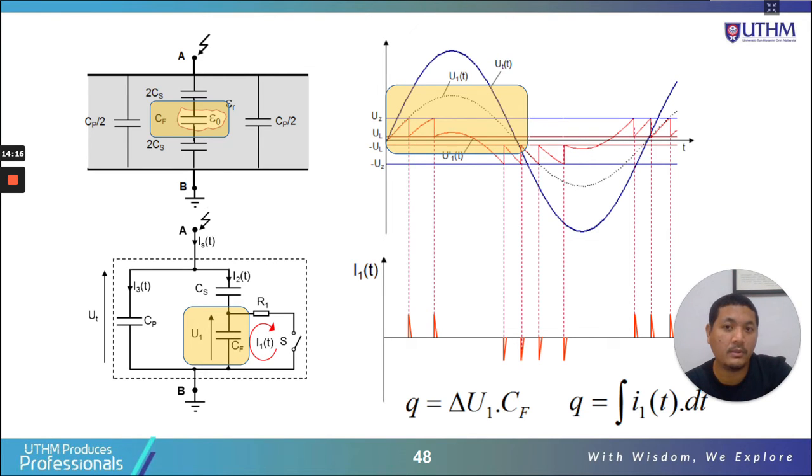When I say discharge happens, it means there is an electrical breakdown inside the void. Electrical breakdown means that current flows inside this air pocket, so the voltage goes down, it's discharged, same as a capacitor.